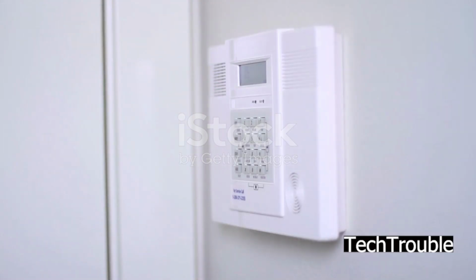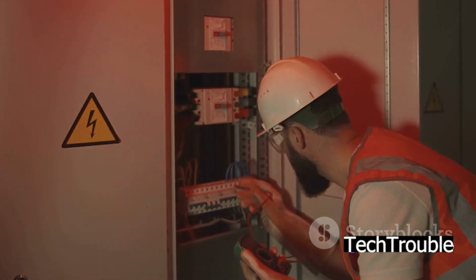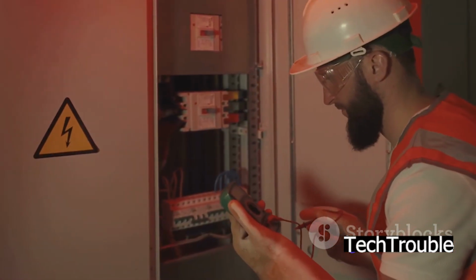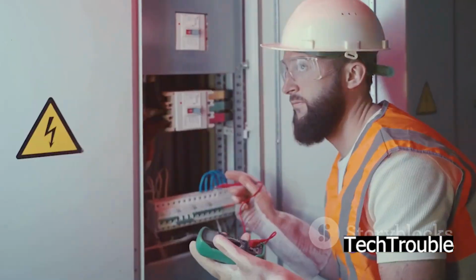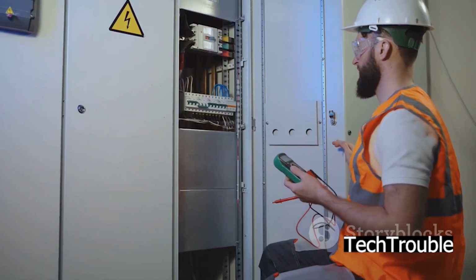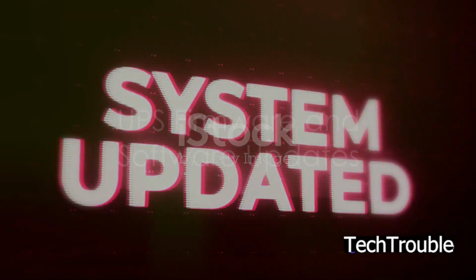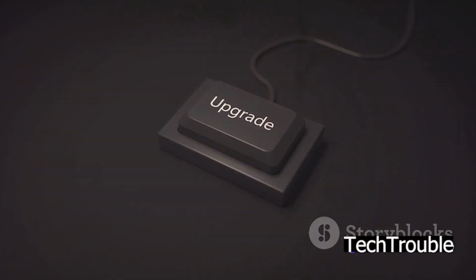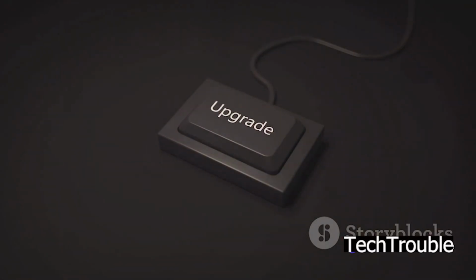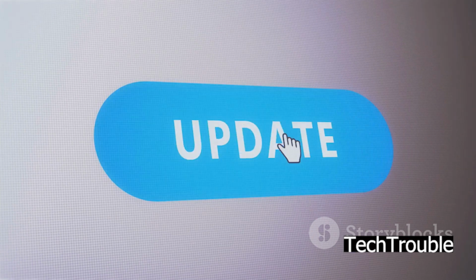This indicates a problem that requires attention. Refer to the UPS manual or manufacturer's website to interpret the alarm codes and troubleshoot the underlying issue, which could include battery failure, overload conditions, and internal faults. Lastly, ensure your UPS firmware and software are always up to date. Regular updates ensure compatibility with your operating system and provide access to the latest features and bug fixes.